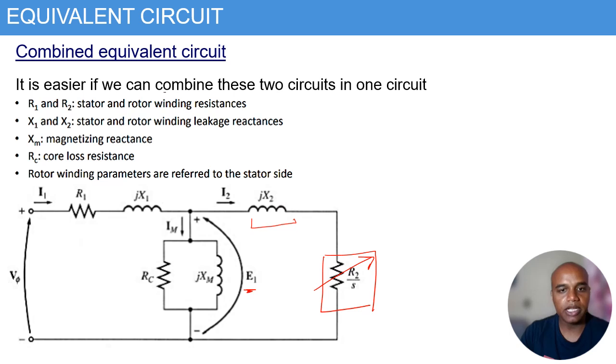So this becomes my A1 if I'm taking the voltage ratio as 1, just like in the case of the transformer. So the only purpose of showing the rotor as a function of slip is to replicate the stationary rotor, just like the secondary circuit of my transformer.